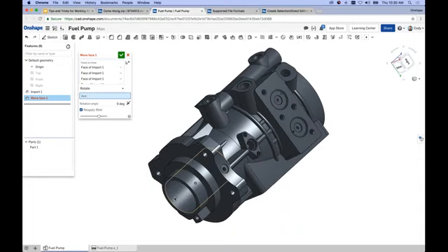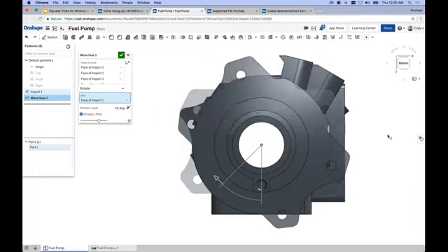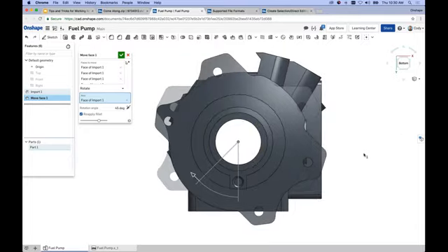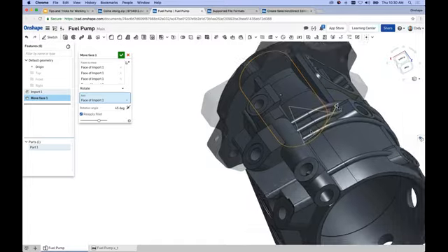And like any axis selection in Onshape, I can just choose any cylindrical face or circular edge. They all work as axis references. And here I can say, what's our rotation angle? Let's say 45, right? Enter, and it's going to rotate the entire flange 45 degrees. It will still line up, it will still merge with the rest of the geometry, right?